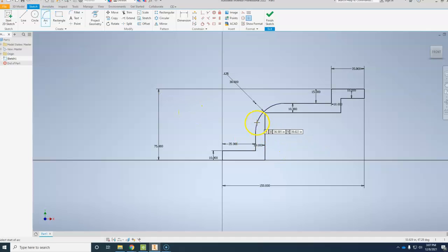We know it needs to be a distance of 10 between the two of those. So this is what we're going to do. We're going to take an arc. We're going to draw it right along where the other one is. That's a 3-point arc. And match it up. There. And then we're going to offset it by 10. Offset this. This. Offset.